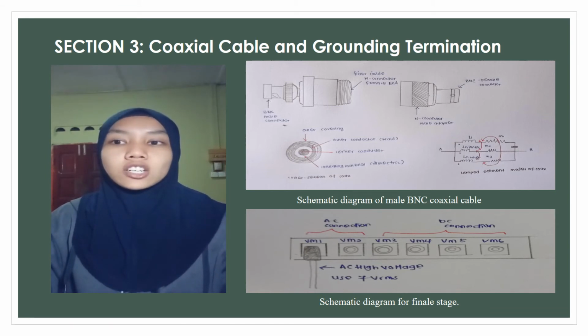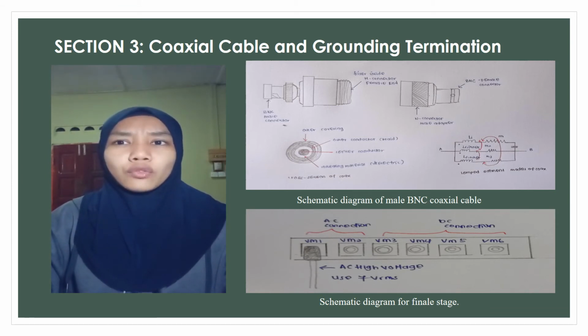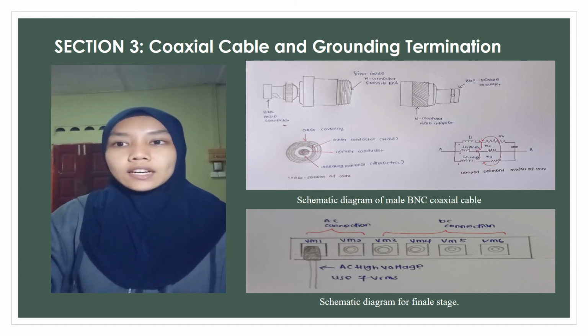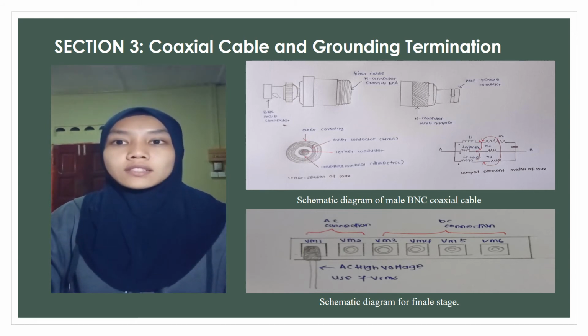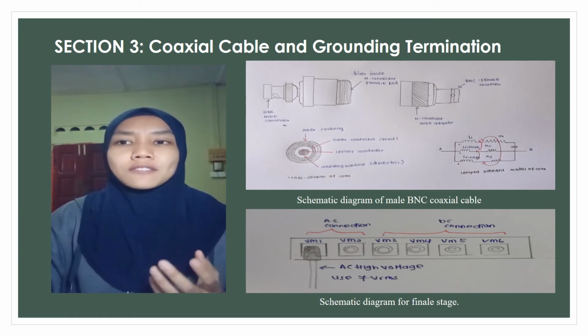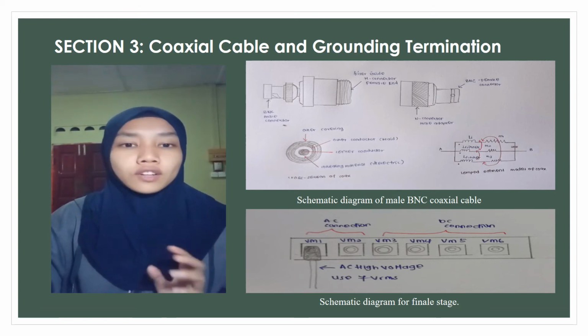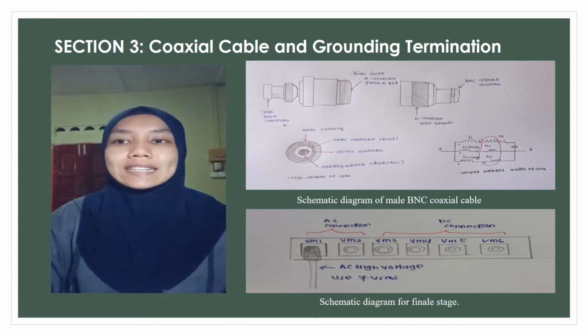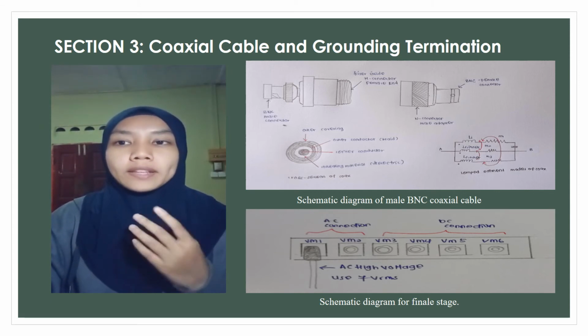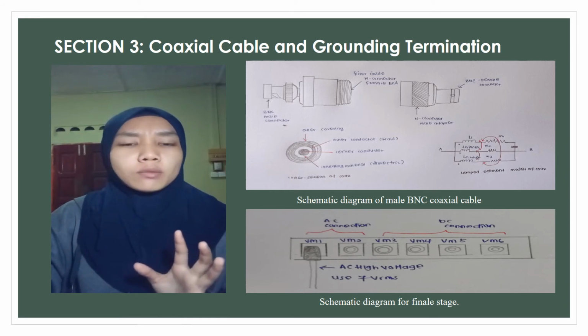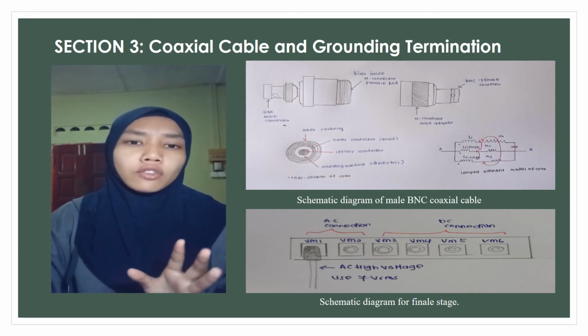Next, BNC connector gender can be confusing, but they can be classified by their gender, if it is plug or jack. Jack commonly refers to a connector with a female electrical contact or socket, and is more often what is affixed in the device or panel, while plug commonly refers to a movable connector, often with a male electrical contact or pin, and it's more often the cable, the movable connector of a pair.